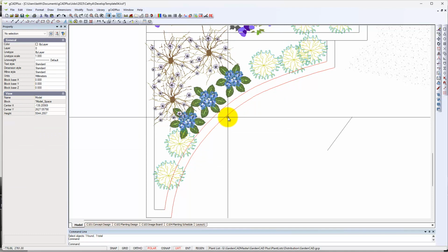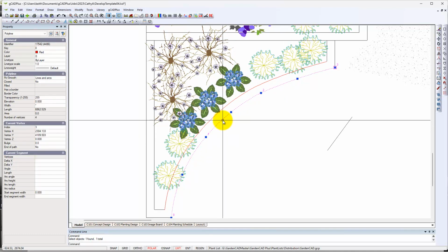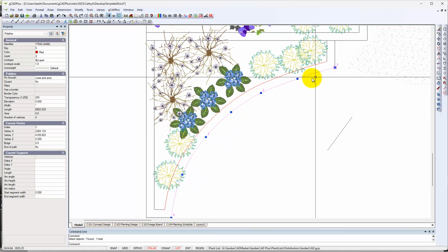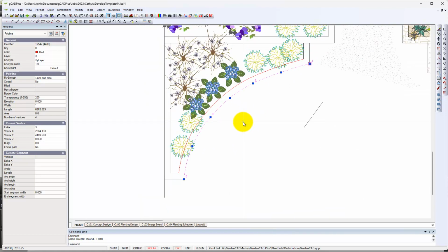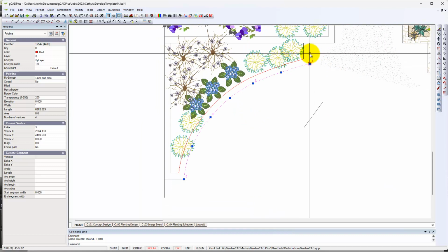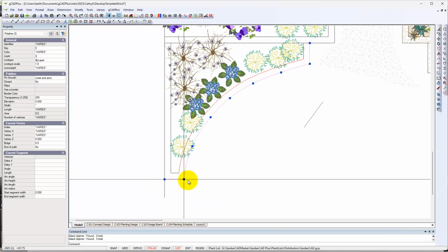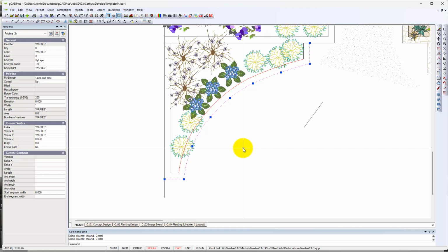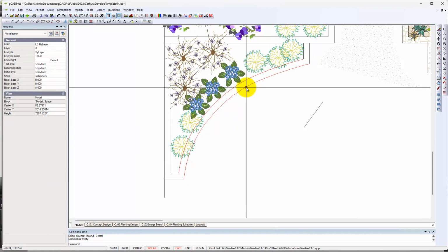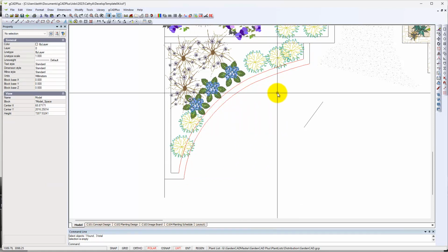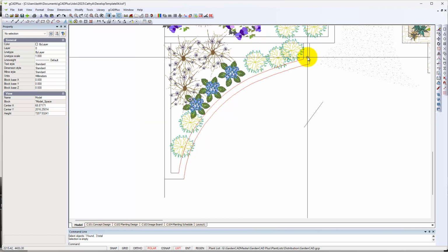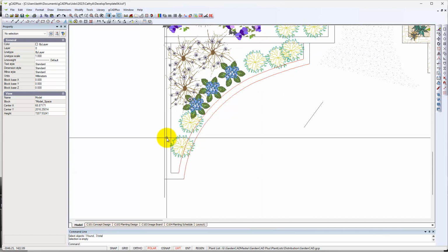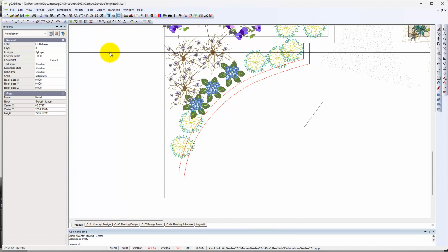Now I've left you with a polyline where I've used the arc option, and if I use the arc option, it does mean that I can join a polyline, and I came upon this problem because that previous one with all those vertices in it, I couldn't join them. But we can indicate that area and hatch it very quickly just by using a small trick.